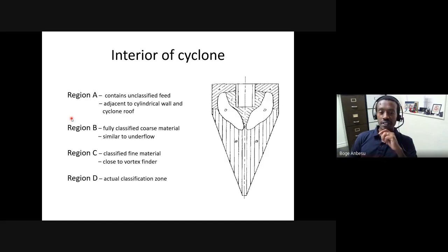So as you can see, this is a very simple operation relatively. As long as you have reasonable difference in particle size or particle density, that should be operated at a reasonable efficiency. If you're very keen to know what goes on inside the cyclone, this is just one cyclone. We don't have compartments actually inside it. There's no compartment or anything. It's just purely based on hydrodynamics inside that cyclone.